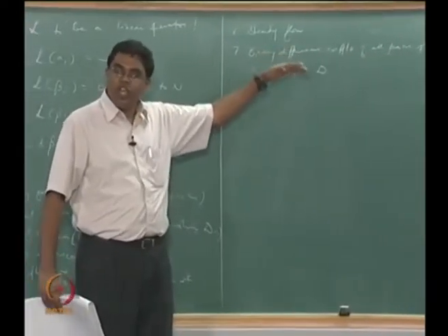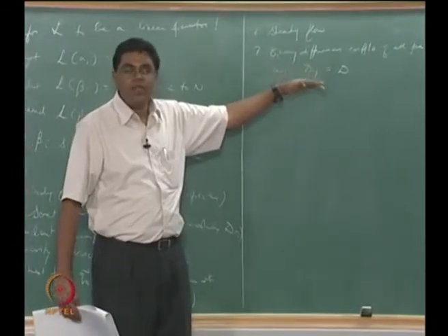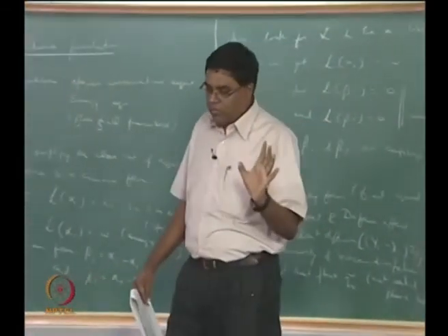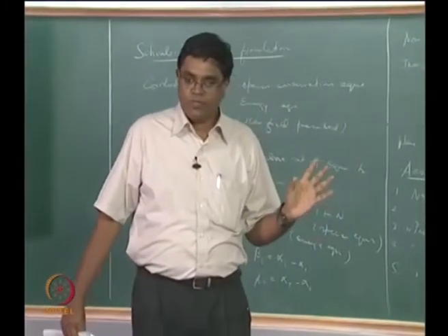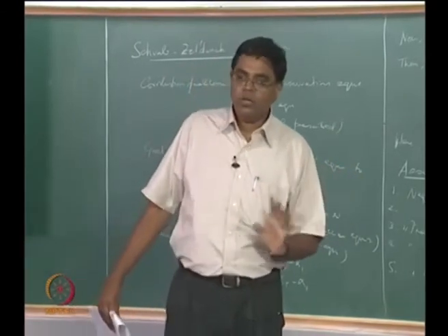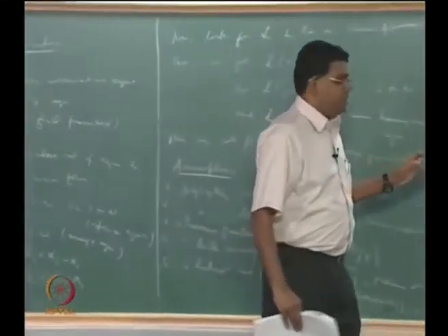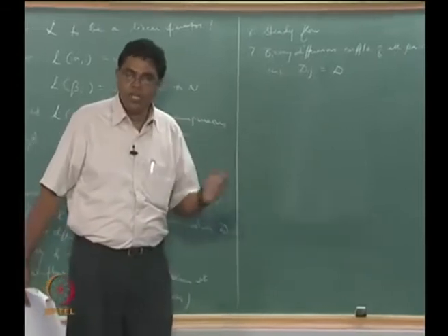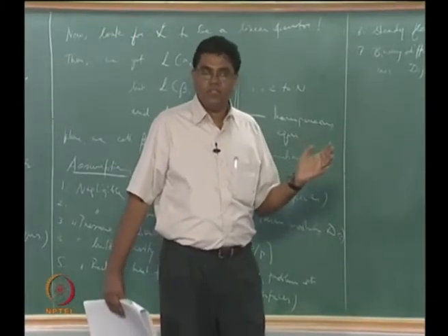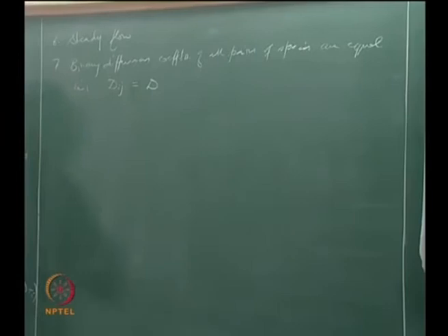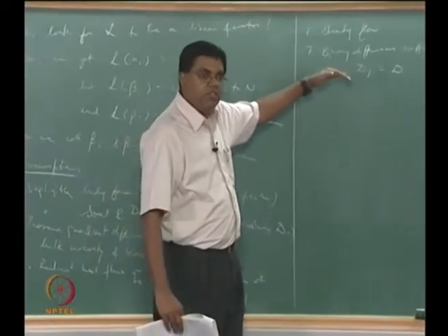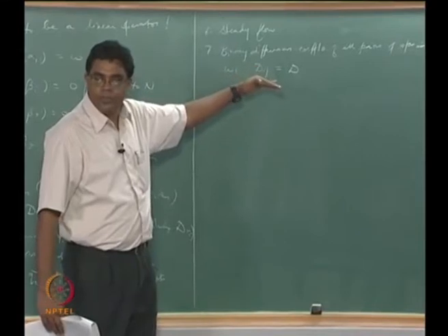Okay, the question is, is it okay? The answer is, not terribly bad. Typically you have to start worrying about this assumption if you are dealing with things like hydrogen as part of your mixture, right. Let us say you had a mixture of hydrogen and hydrocarbon going through combustion, then the pairs of species involving hydrogen may typically have a higher diffusivity when compared to others, and then that is markedly different, whereas if you are dealing with most species of the order of the same molecular weights, not necessarily equal, you can expect that this assumption is a very reasonable assumption, not bad at all.